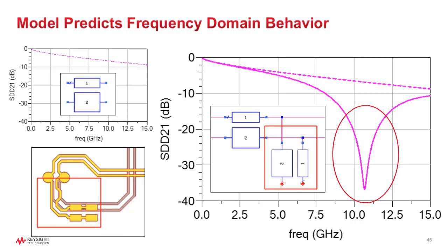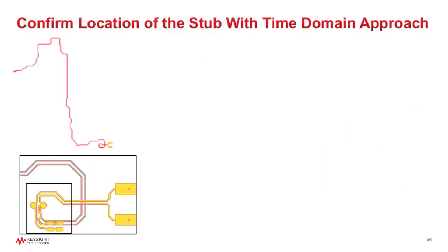I'm connecting the USB signal trace to the ESD diodes. So that's what's happening here. So we know how to troubleshoot it, but let's take another look. We've been in the frequency domain for a little while. Let's take a walk in the time domain, where we'll use time domain reflectometry to look at the same trace, looking at it from this angle.